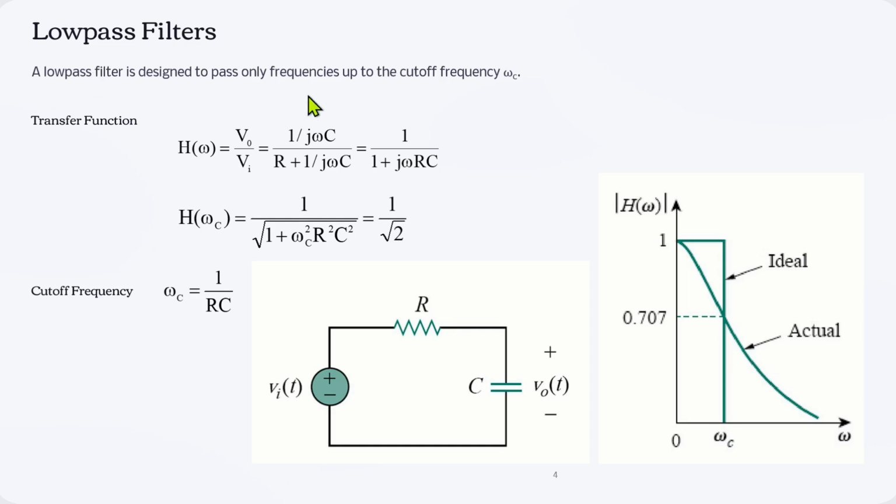The filters that we are discussing here are passive filters. So they use only components like resistors, capacitors and inductors. They would not have any transistors or any kind of op-amps, because if we consider transistors and op-amps in our filtering circuit, then it becomes an active filter. That is why, as you can see in the diagram, we have two components. One is resistance, the second one is capacitance. So this circuit will generate the low pass filter.